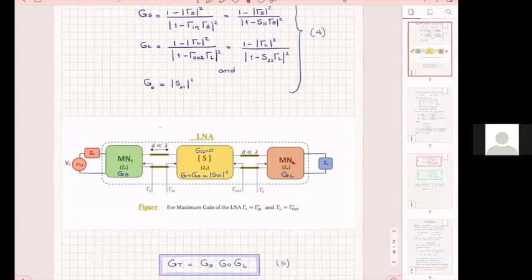But here is what happens. If you only have lumped inductors and lumped capacitors, your frequency change comes through the omega. So a reactive part coming from an inductor is j omega L, and the reactive part coming from a capacitor, in impedance form, is 1 over j omega C. So they vary as omega or 1 over omega.